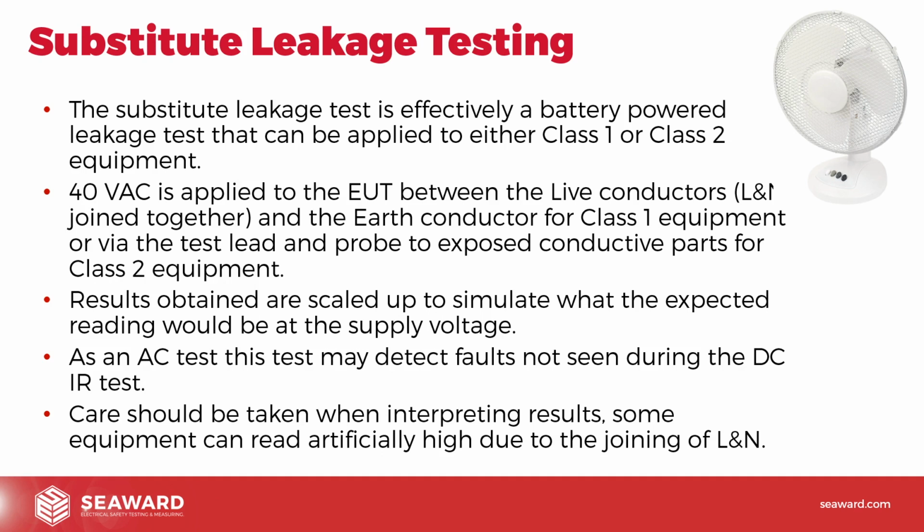So if you're not certain about this, obviously you can do an insulation resistance test, but you can also do one of the mains powered leakage tests that we talked about to try and verify whether it is a true reading or whether it's actually just due to the way the test works out. But it's one of those things that as a competent person, if you're aware of it, you can deal with it.